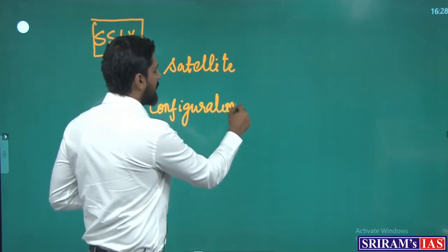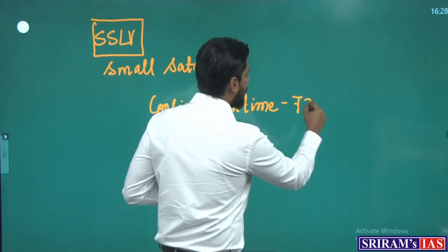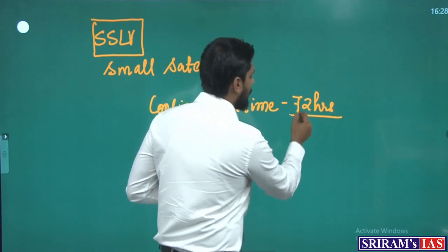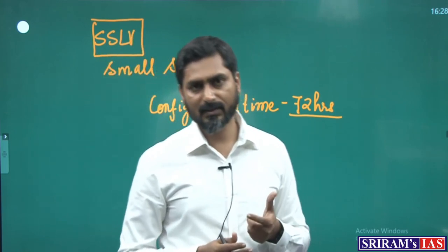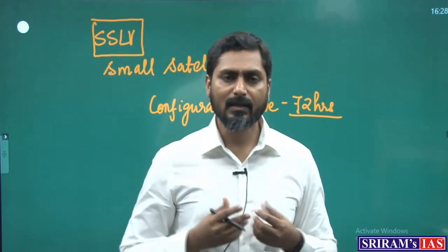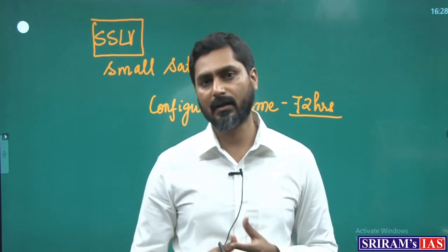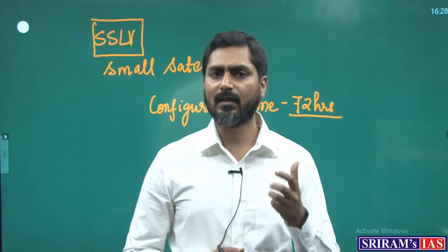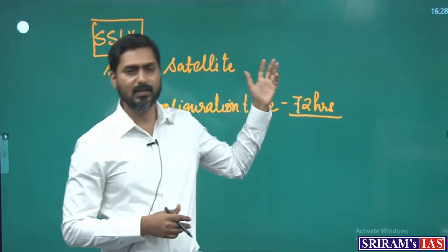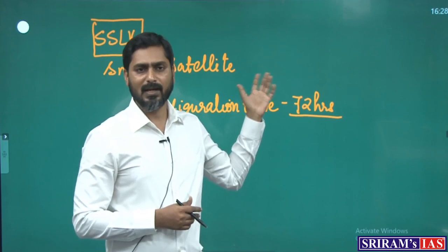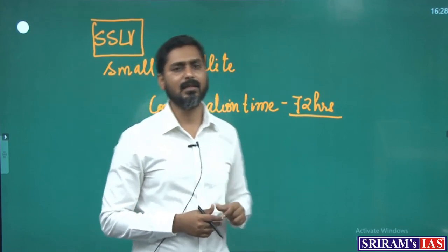The configuration time is just 72 hours. That is why India or ISRO believes that by having this type of launch vehicle, we can increase our market share in the small satellite launch service market. So some of the technical features of SSLV is that it is not using any liquid engine, it is not using cryogenic engine, it is using only solid engines, and it has 3 stages.